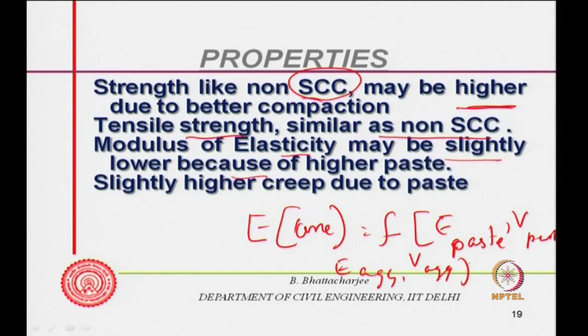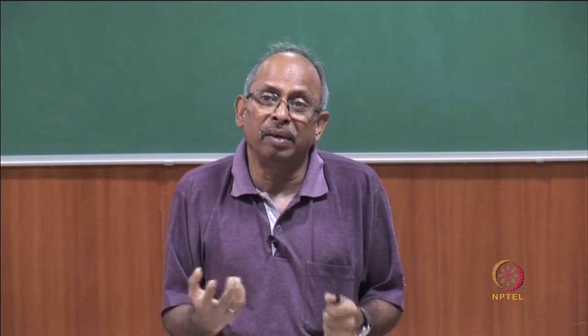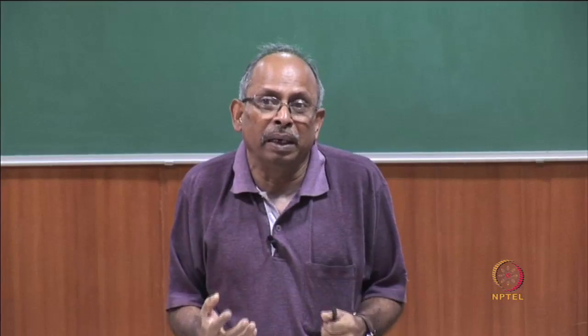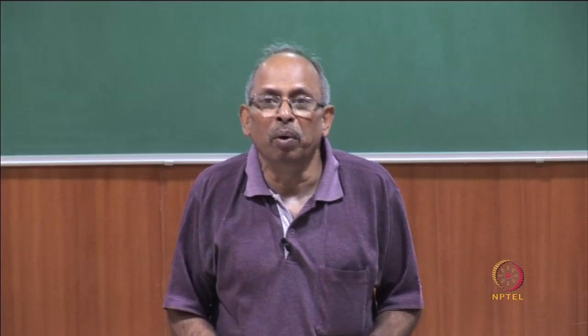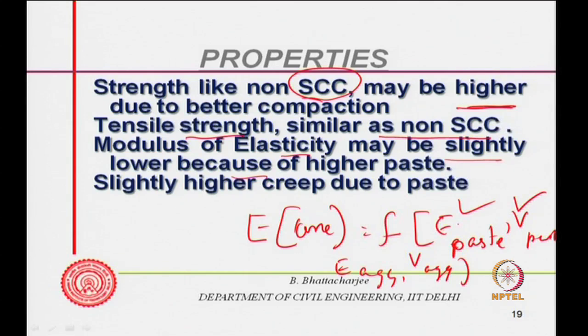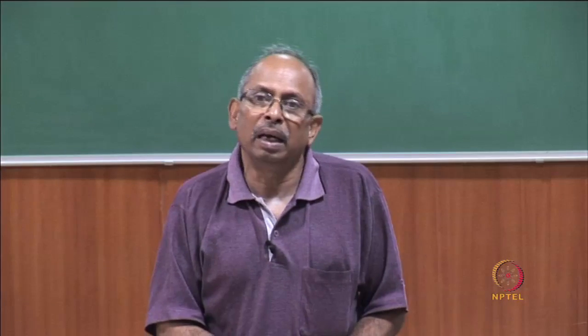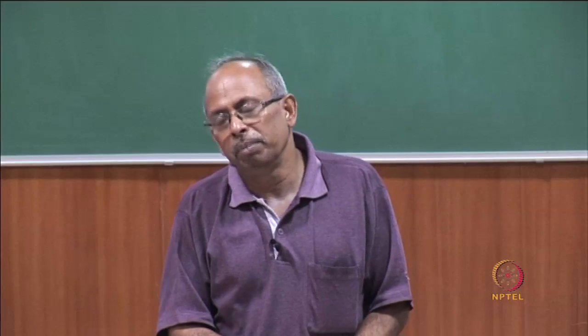So, since I am increasing V paste, it will depend upon E of the paste. It will depend upon the situation where E paste is high, that means in a high strength situation, if you have self compacting, then modulus may not be lower. So, it could be affected somewhat, slightly lower, higher paste content depending upon E of the paste.